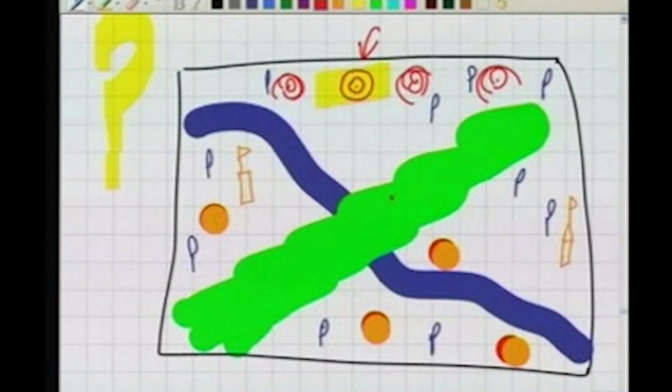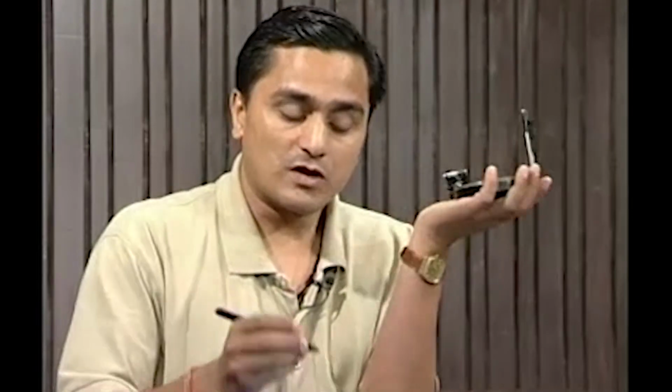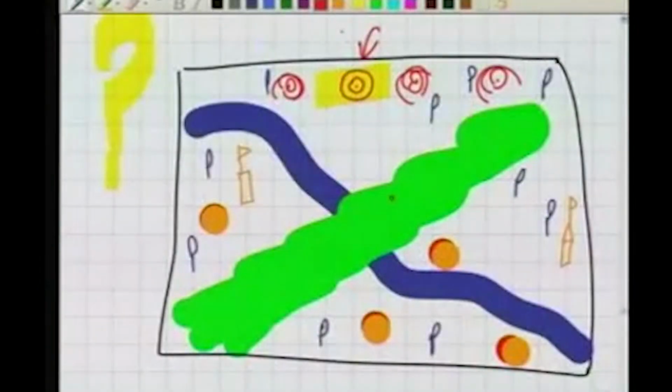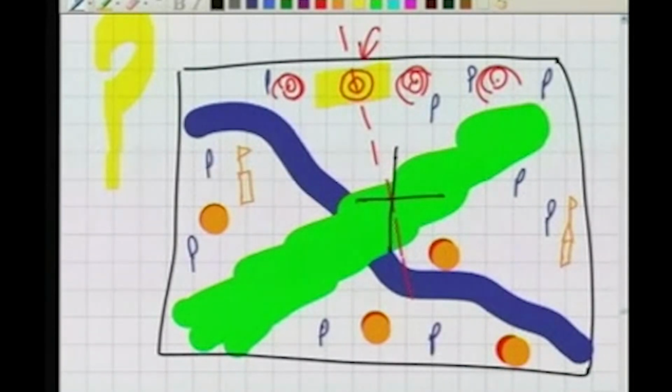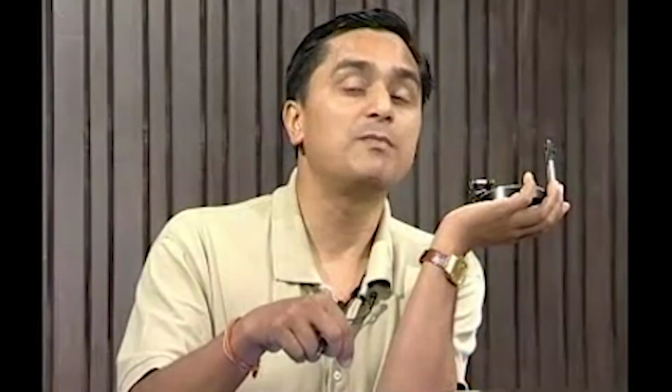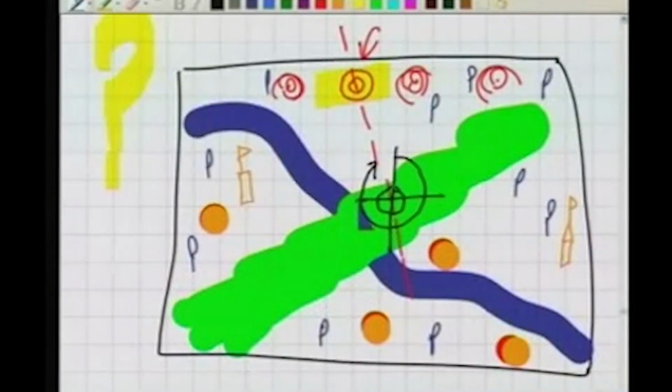Once we have located ourselves on the map by the method which we have just done, what we will do now, in our map we will draw a line and we will measure the fore bearing at this point where we are standing for this object. So that is the value of the fore bearing which we are computing from the map. We know that we are here. So we are computing this fore bearing to a particular tower.